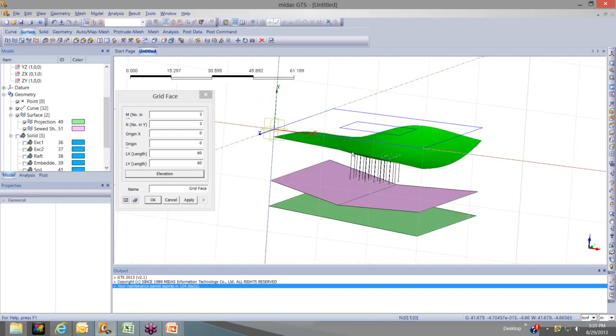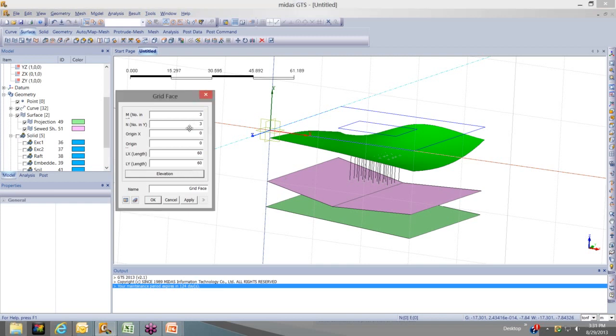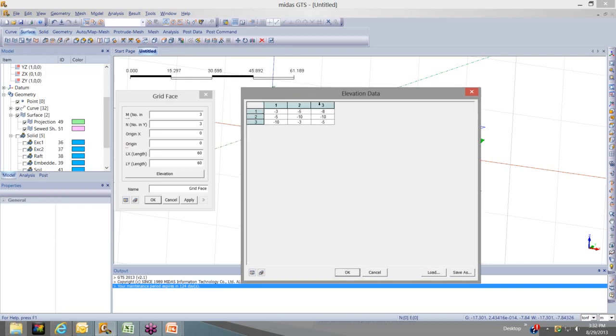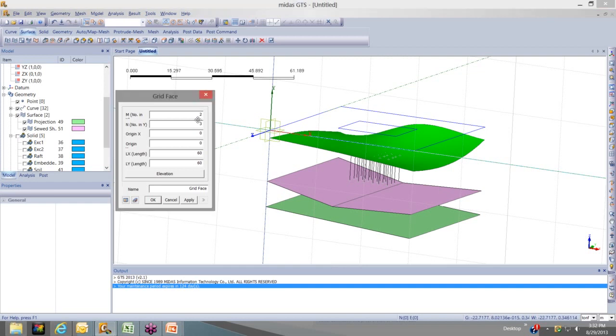And then just using this type of application, I could create something more detailed or more contoured. So this option becomes increasingly useful for larger scale projects where you have very varied contour diagrams that maybe you'd want to import. So it's really important that if you have a type of project like that, you understand how this grid range works. And also, because I know there are certain programs out there like contour modeling, etc., that'll take all of your contours and put them in spreadsheets, using this option you can just copy and paste those coordinates directly into your elevation data, and it'll be created in your program. But once again, this is a simpler, smaller scale project.